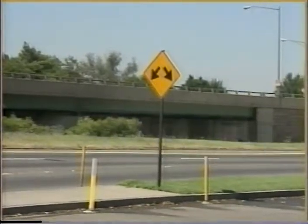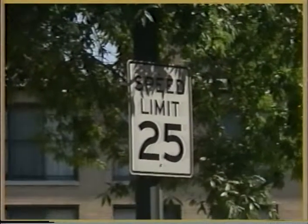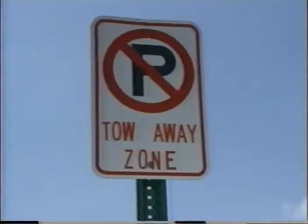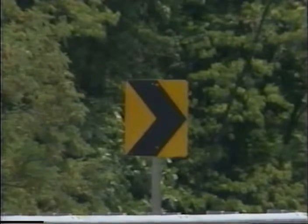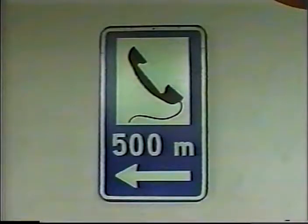There are a series of standard shapes that are common to all three systems as well. The diamond is used for a majority of warning signs in the U.S. and Latin American systems. In the European system, it means a priority road. The rectangle has a couple of meanings. In the U.S., with the longer dimension vertical, it is used for a majority of regulatory and some warning signs. The European system uses this shape for informative signs that tell about services. The Latin American system uses the shape for guide signs telling of services.